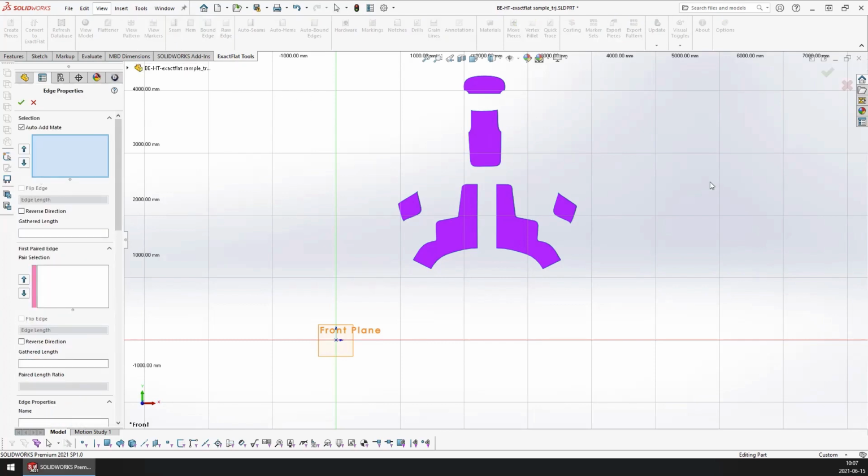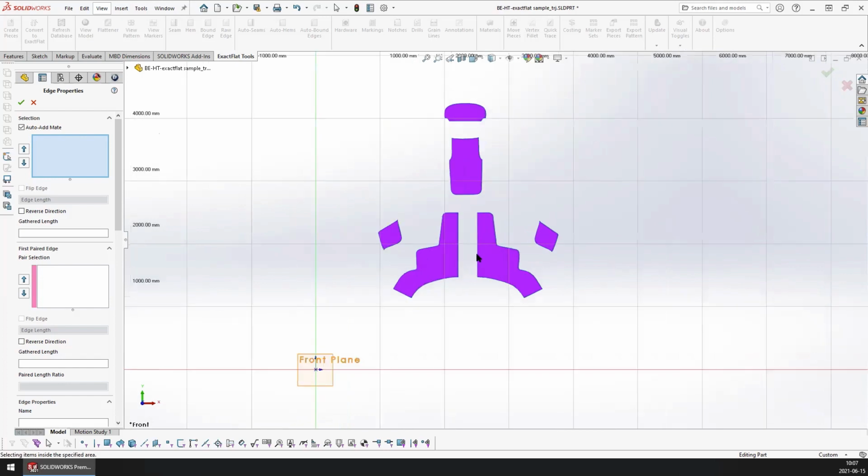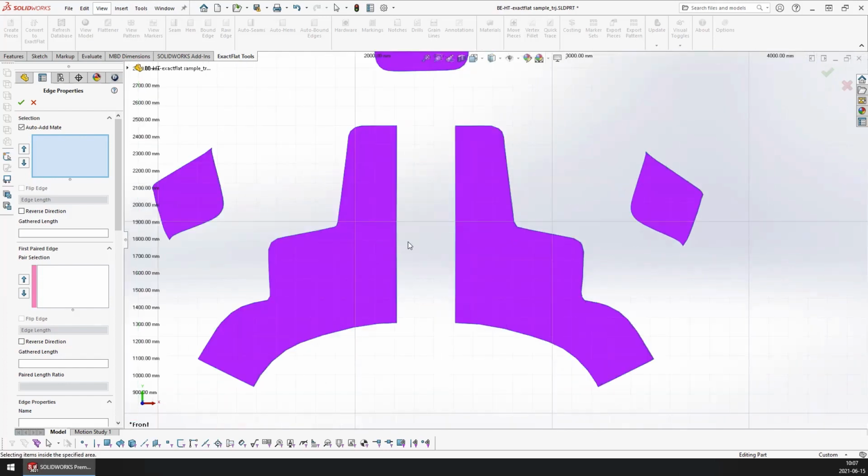It's very important that you think of seams as individual sewing operations. That is, you have to create your seams the way they would actually be sewn together in the assembly process. A lot of the time, people will tend to just rectangle select everything, and if you do that, you will probably succeed in adding your seam allowance to your pattern pieces. However, none of your notches are going to align, and that's simply because you're considering every single edge in your document here as one side of a sewing operation. So you need to consider this as a sewing operation, and when we start selecting our edges, you want to select them in the order that they would be sewn together.